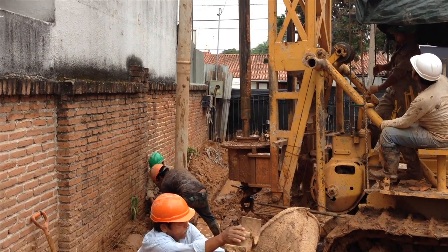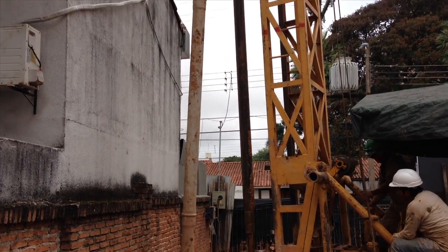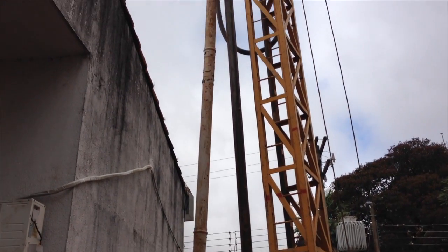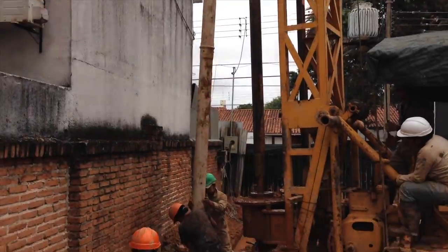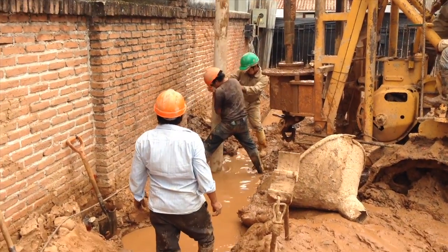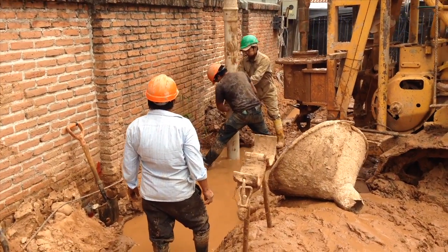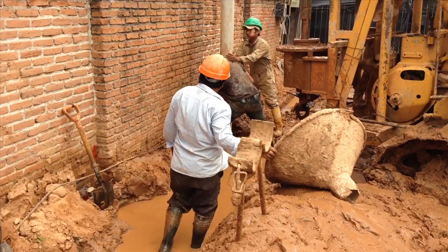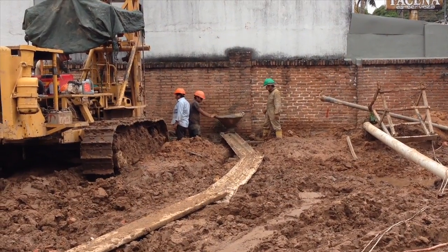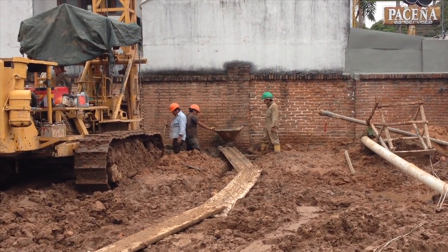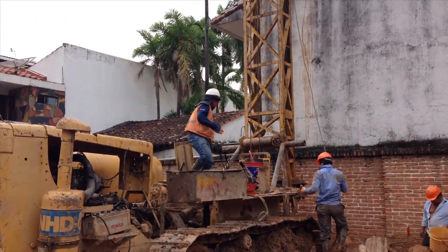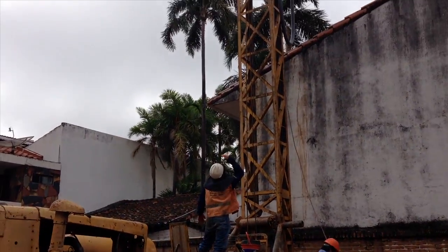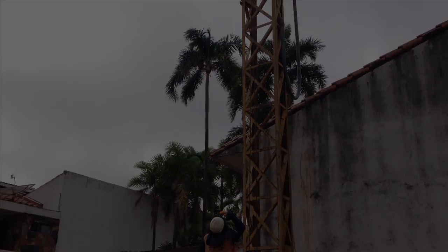Conventional deep foundation method. In Bolivia, the most common pile foundation method during the past 30 years has been the auger piles, drilled and concreted under support of bentonite slurry. As a result of the use of cheap and crude boring tools, the quality of pile installation is often low. The most important problem is the lack of quality control and monitoring of the installation process, which results in high factors of safety and poor project economy.